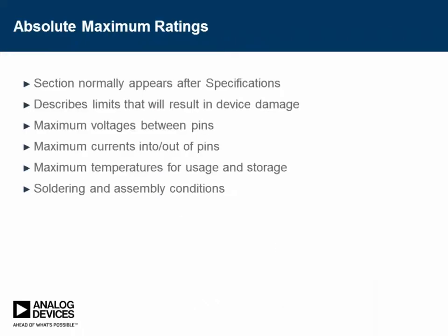Now the next section, which is very important, is the absolute maximum ratings. This section on our data sheets usually appears after the specifications. And this will describe the limits that if the product goes beyond those, it will result in device damage.